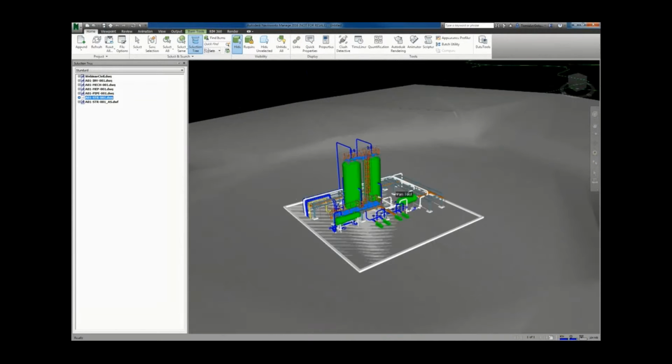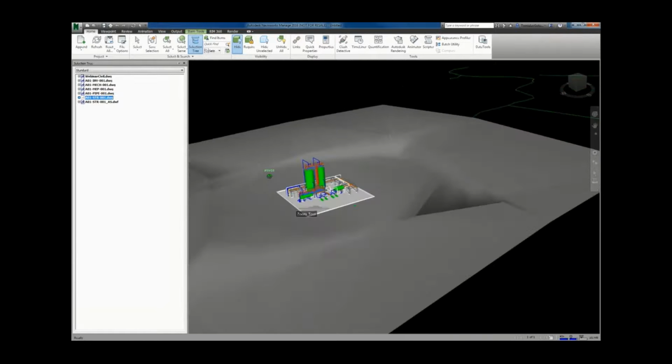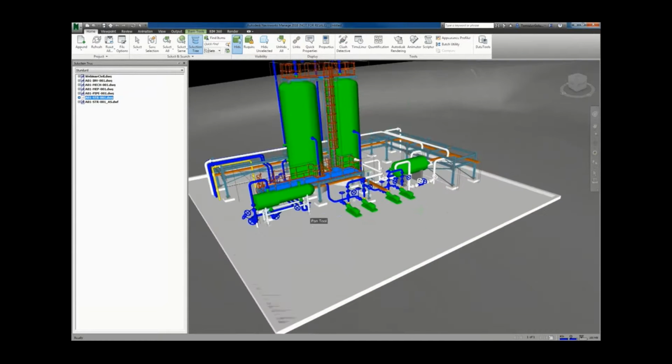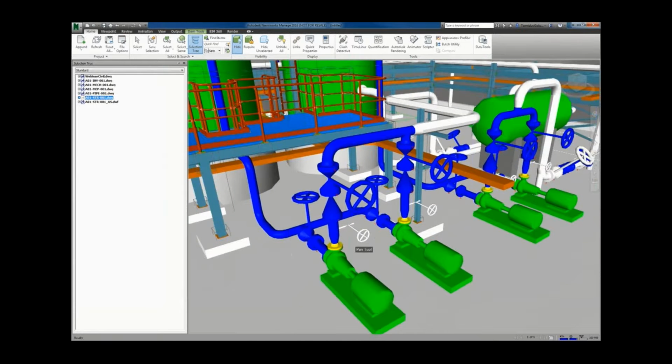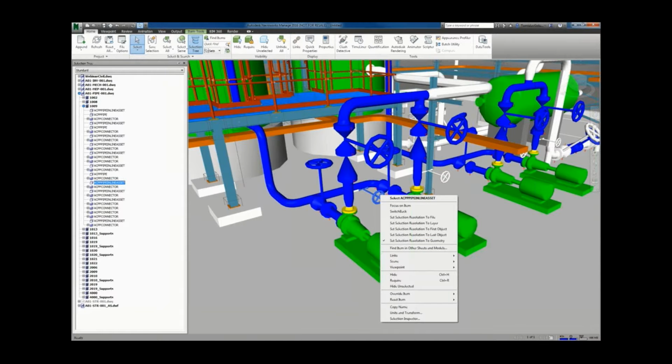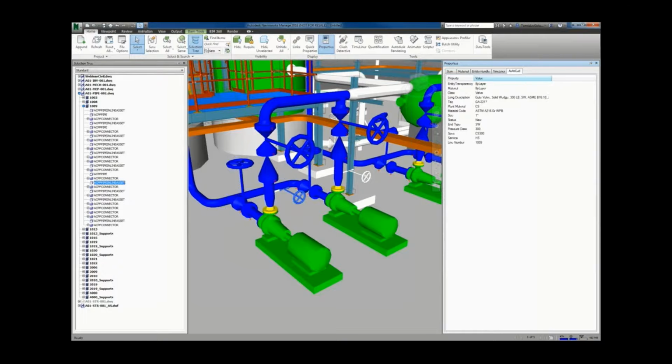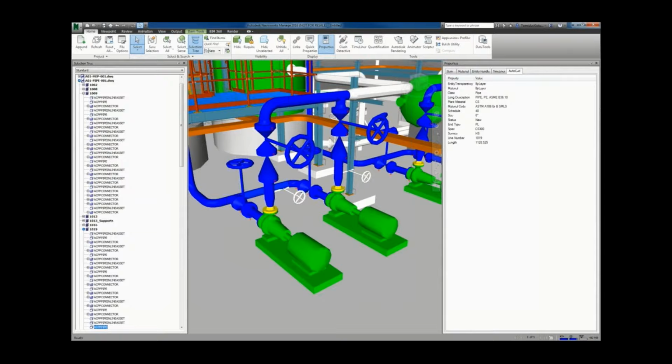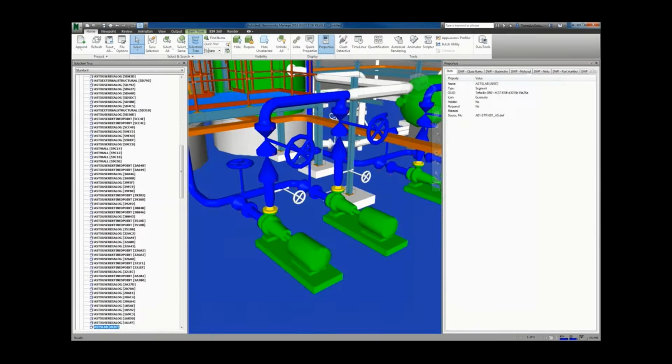So what is Navisworks going to do for you? The first one is obviously just walking around the model. So we can go through, check out a few things. We can go through and identify items or objects. So if we look at the properties of it, you can see here that is a gate valve. It has a tag of GA221. Looks like it's been copied, so it hasn't been updated yet. It's a 1-inch line. Also, if we click on the pipe, yeah, it's A106 Grade B seamless, Sched 40, 6-inch in size as well. So this is, I guess, the main reason you'd be using Navisworks.